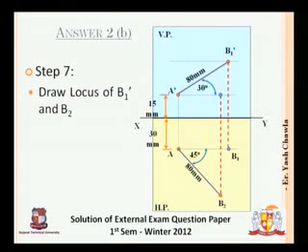Now we'll just draw the locus as a simple locus, first on B1 dash and then on B2. Now this locus is very important, as this will be housing the endpoints of the projectors, the projections, that is the top view and the front view. Both the views will be marked on this locus. The endpoint will be marked on the locus.